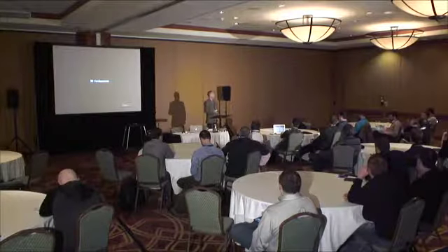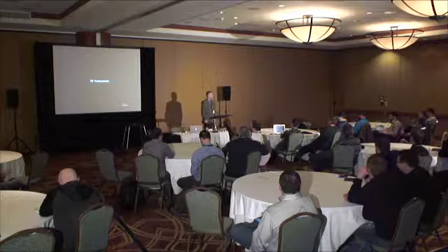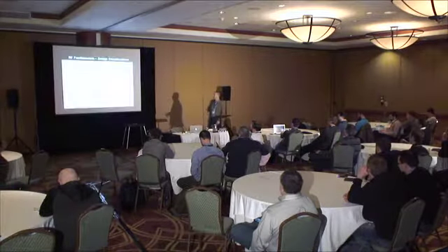It'd be similar, and you pointed it out on the high density stadium design when we start talking about concrete. If I'm going into an existing stadium, I may do some spot surveys to see, well, what is my loss through this concrete? How is the concrete? What's the water content? That kind of stuff. So very similar. It's a good middle ground, in my opinion, of cost and time, and still getting some accurate data. Yep. All right.